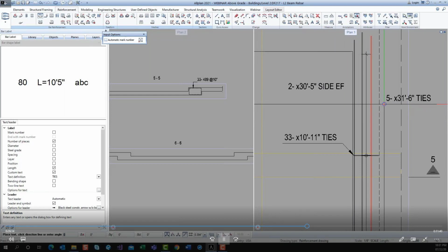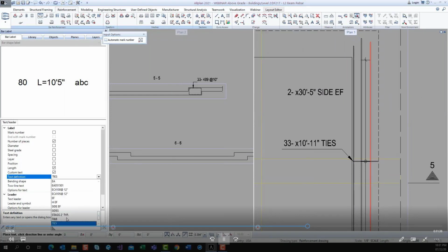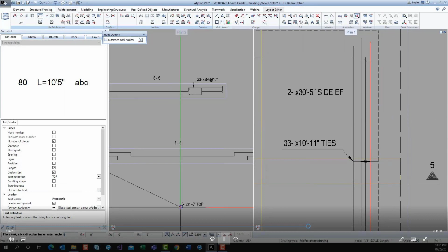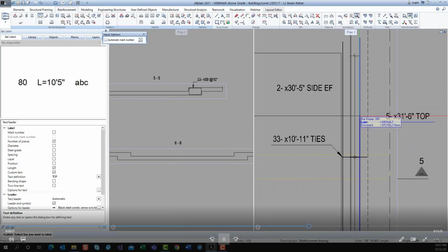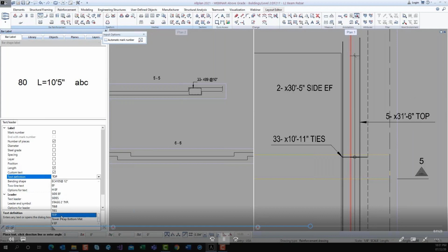I'm going to go ahead and apply a label to the outside. This one here happens to be top bars. And I'm going to apply a label to the bottom bars. I'm going to label all this. So you can see when I do the mirror, the labels will go with that. Now they'll maintain the orientation to the bar, so they might be turned 90 degrees. And in some cases, it's okay. Sometimes you might just have to rotate them 90 and everything else will follow your arrows and so on.